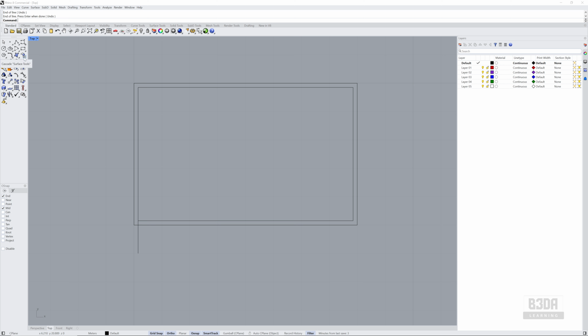It's one of the most simple ways to create this type of drafting in AutoCAD as well. If you right click here on the command line, you will see the last options that we entered, and one of them is the offset curve. You don't even need to open the menu again. I'll be making an offset with 0.15. Click here, click on this side for the direction.